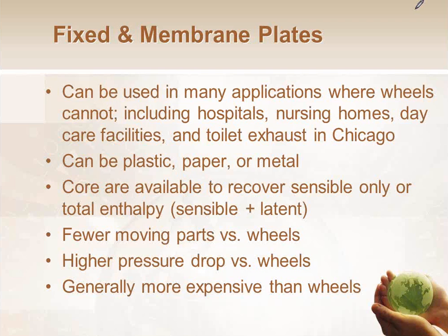Fixed plates can be either paper, plastic, or metal. The most common sensible ones are made of metal. The most common latent recovery ones are made out of paper that has a wicking effect to them. So if you've ever taken a glass of water and stuck a string in there and held it up there, you'll notice the water will wick its way up the string. That's kind of how I explain to people how these cores work. It wicks the moisture through from one airstream to the other, but it is the moisture only. It does not take through any of the air molecule pollutants.